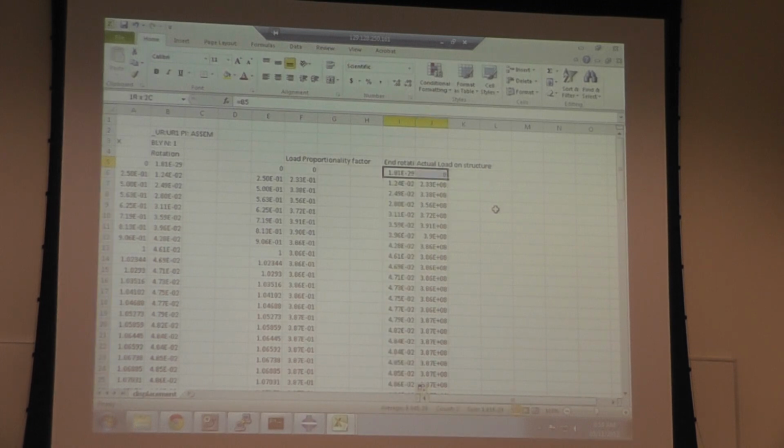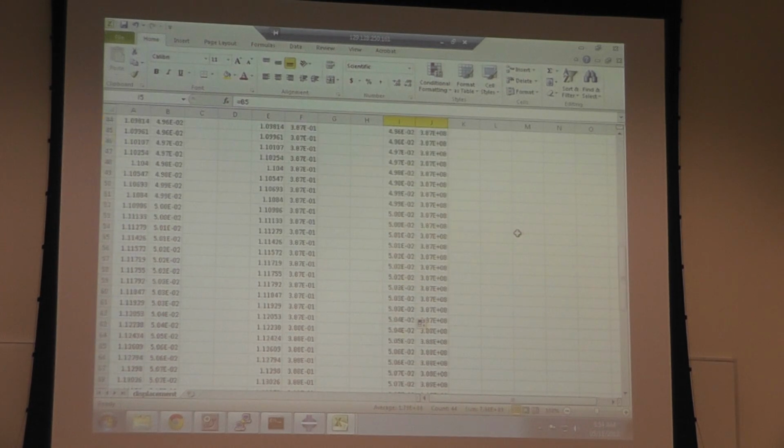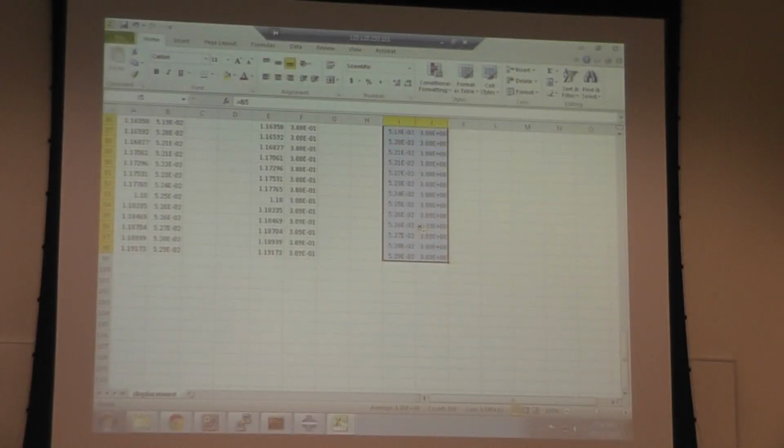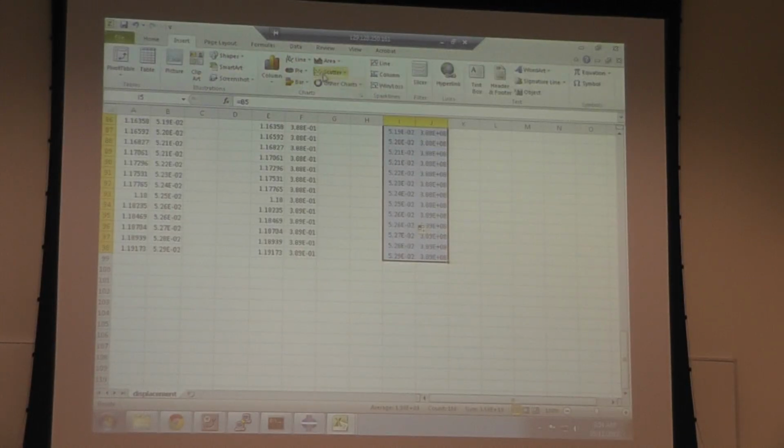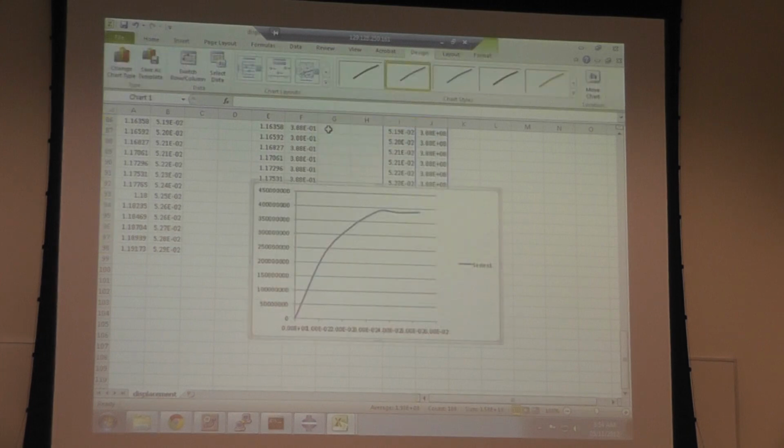And so you can plot the moment versus rotation. You can see that the initiation of this is elastoplastic buckling. The model plastified early, but then at some point it dipped, and then it was moving horizontally, where the rotation is increasing but the moment is not increasing anymore.